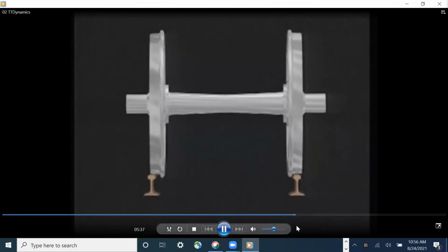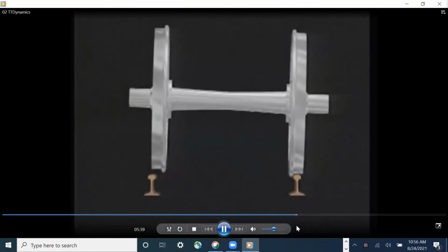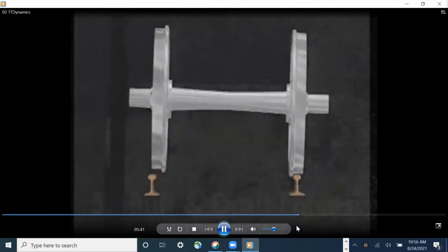Rail cars are of different lengths and have drawbars of different lengths that create lateral coupling forces on curves. This results in high opposing lateral forces being transferred to the truck assemblies, which can force the rail out of line or even derail a car.